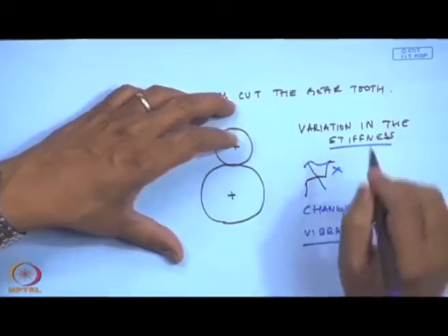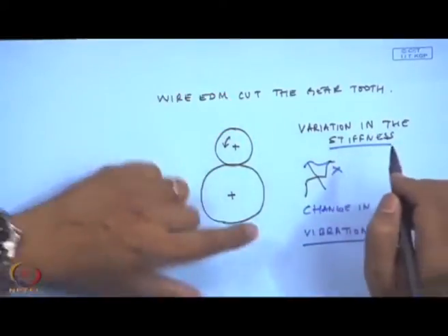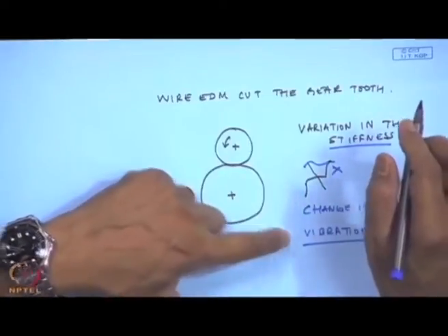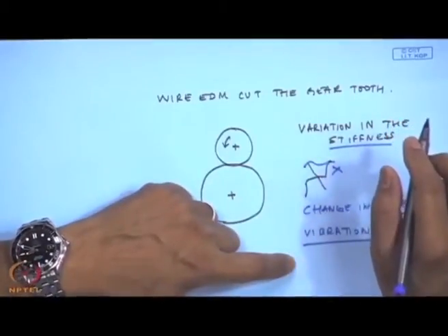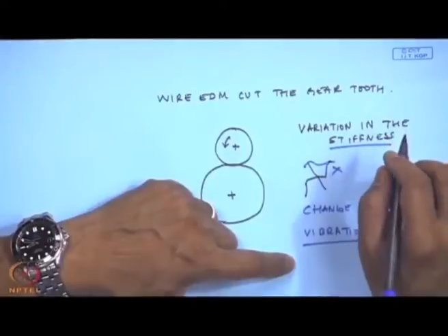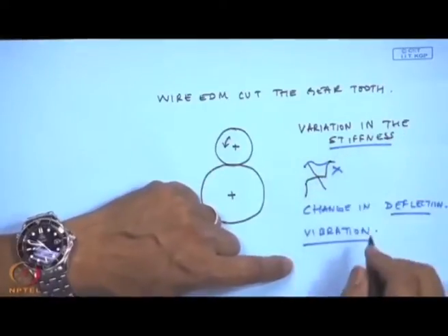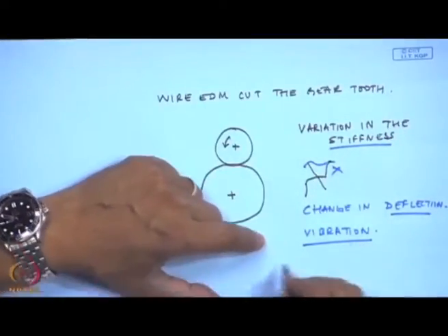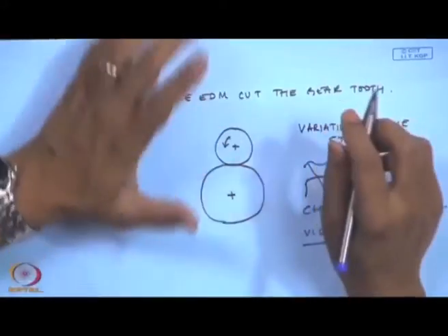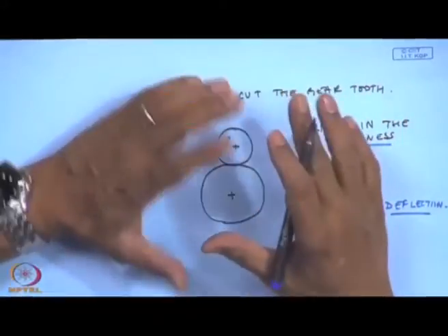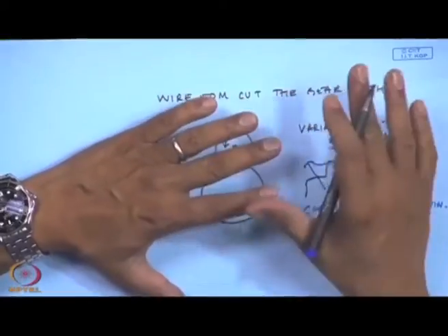Okay. So, because a vibration has been generated because of a gearbox fault, we will see that the fault has occurred. One is the gear oil conditions in terms of its temperature and physical changes because of the wear debris particles.